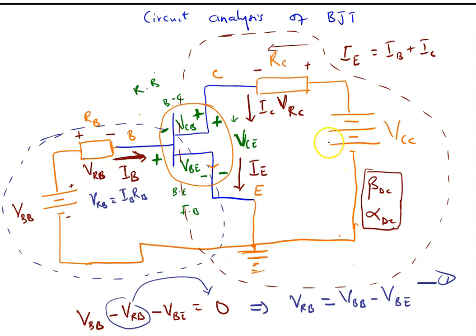The VCC, which is a rise in the voltage, VCC, minus VRC, minus VCE. That is it in a closed loop. The voltage here minus the voltage here minus the voltage here, going back, is equal to what? To 0. Are you okay?